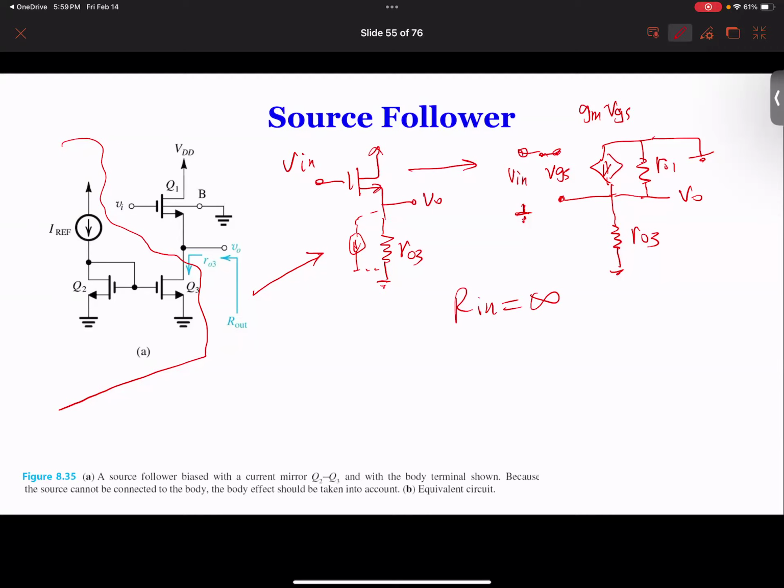The next thing we want to find is the gain and the output resistance of the whole circuit. If we want to find the gain, we need to solve for VO in terms of Vin. In order to find output resistance, we need to connect a voltage at the output, basically here, and find out how much current flows, and then we can find it. So let me do that.